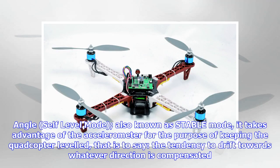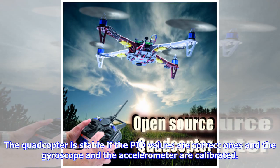Angle, self-level mode, also known as stable mode. It takes advantage of the accelerometer for the purpose of keeping the quadcopter leveled, that is to say, the tendency to drift towards whatever direction is compensated. The quadcopter is stable if the PID values are correct ones and the gyroscope and the accelerometer are calibrated.